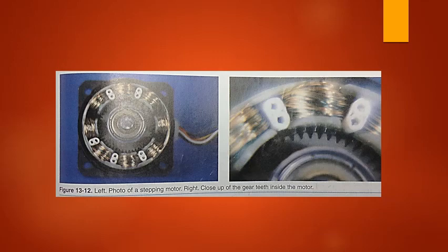The rotor is a permanent magnet with a gear-like construction, but the number of teeth does not match that of the stator. When one of the stator windings receives an electrical pulse, the rotor only turns its teeth far enough to line up with the energized teeth in the stator. The speed of the rotor is determined by how fast the power is pulsed. The direction of rotation is controlled by the polarity of the electrical pulse of the stator. Once a certain position is reached, the magnetic pull of the rotor to the stator holds the rotor in position.